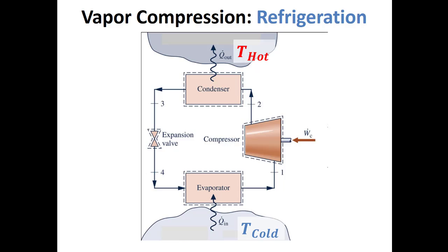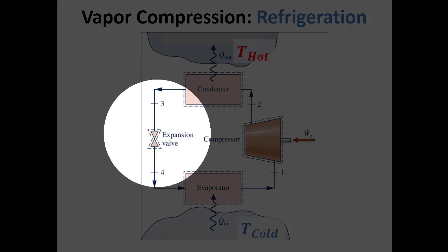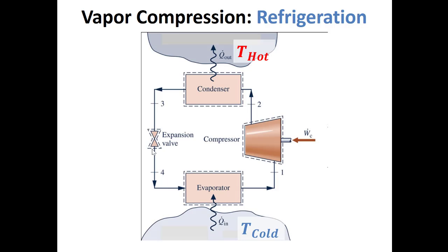An expansion valve may be just a really thin piece of tubing that your refrigerant flows through, so you get a pressure drop. There are different ways to construct these, but that's at least one way. So what we're getting here is a pressure drop, just like across a turbine, but there are no blades inside this expansion valve. We'll see how we treat this, but it's treated a little bit differently than a turbine is.